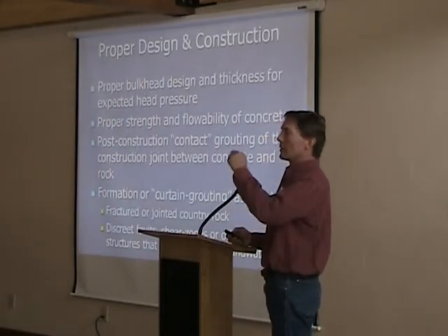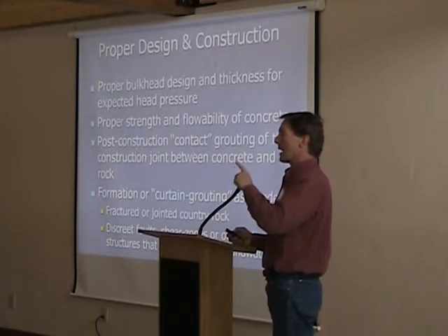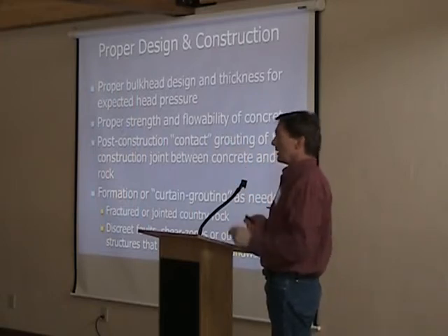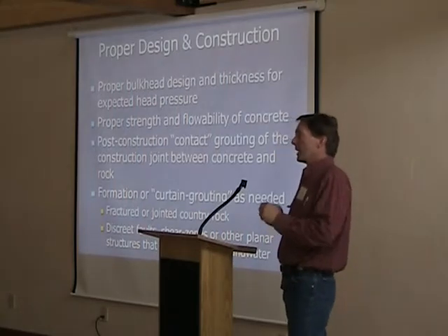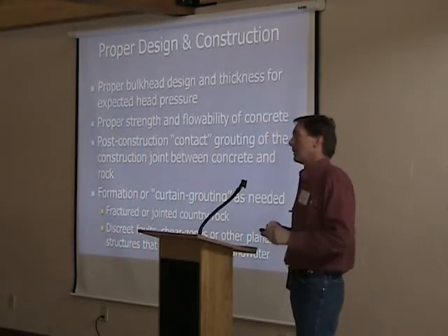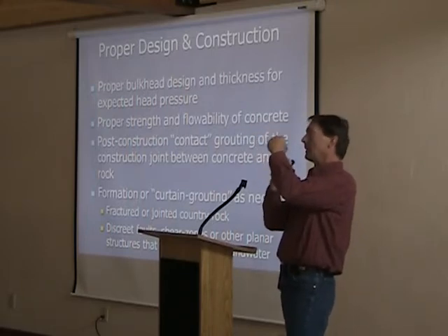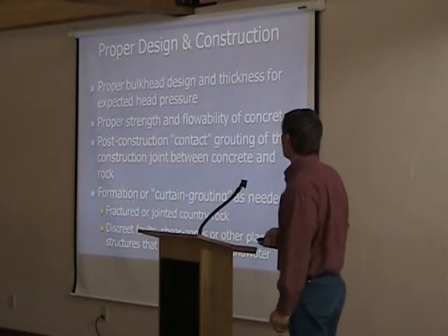And of course, the other thing we have to make sure of is, once you place that concrete, you've always got to contact grout your construction joint, because all concrete, no matter how well you formulate it, is going to shrink once it cures. And if you don't treat that gap between the concrete and the rock after you put the plug in, it's going to leak pretty bad. So we got to make sure we do that.